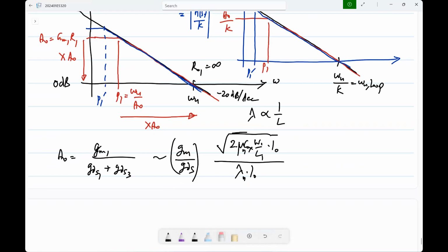What is the gain that you want from an op-amp? Infinity. Of course, you won't get infinity, but you want large values, right? So typically with a single stage, you may not get a large enough value. So we have to change the topologies in some way. Increasing the length works, but if you have a gain of 20 and you want to make it 200, this is probably not a great idea, because then you have to increase the L by such a large factor, and W also, the circuit just bloats up, and it probably becomes so much slower that it's useless. So you have to find other ways of increasing the gain.